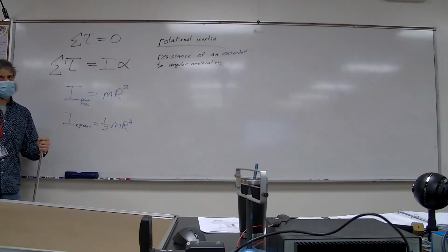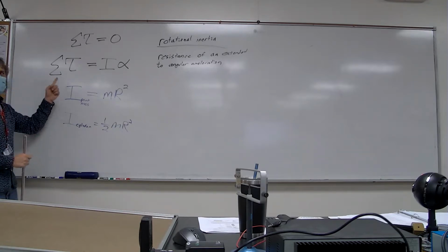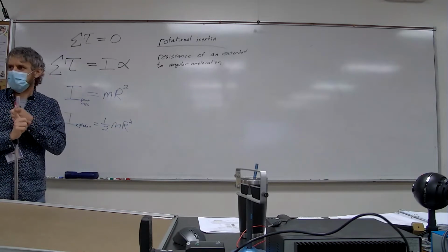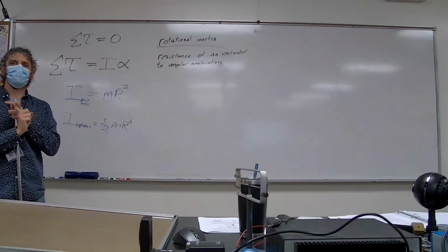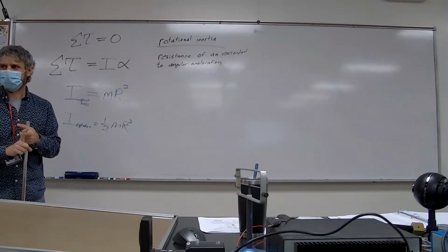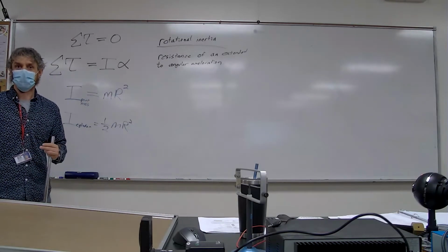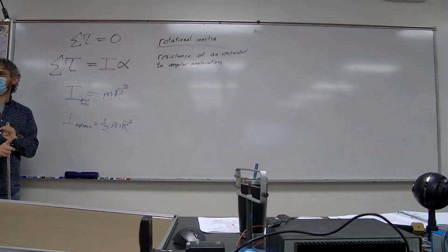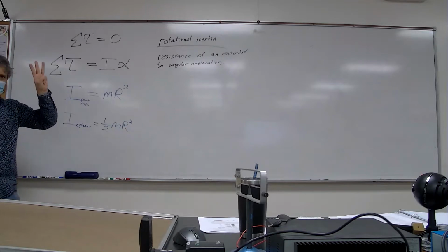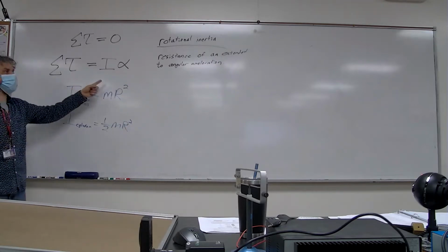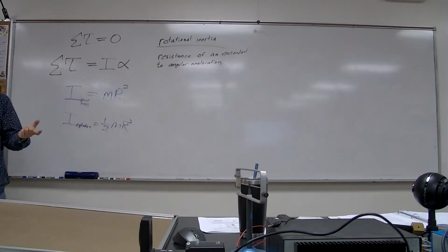Force is technically one quantity. Torque is due to the force, but it's also due to where the force is applied on the object, which dictates where the lever arm is. And it's also due to the angle that that force makes with the lever arm. So torque is due to three separate quantities. So already Newton's second law for rotation is more complex because of that.